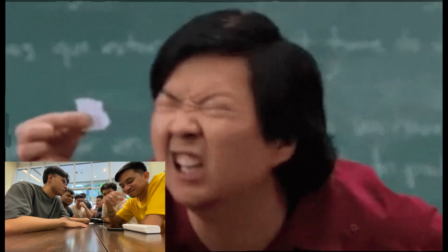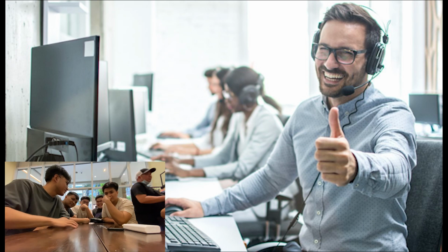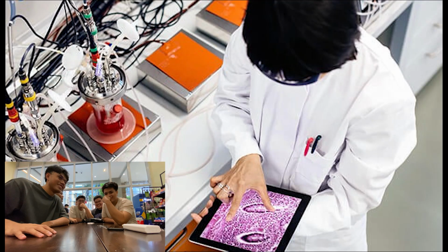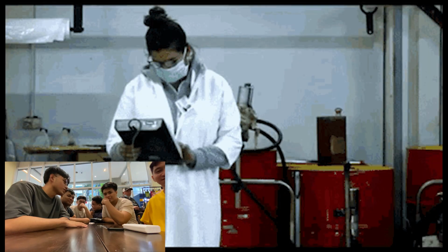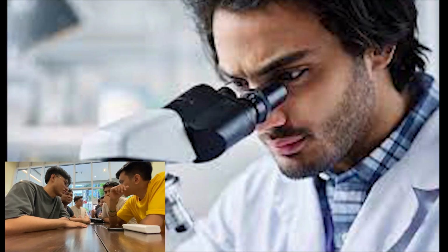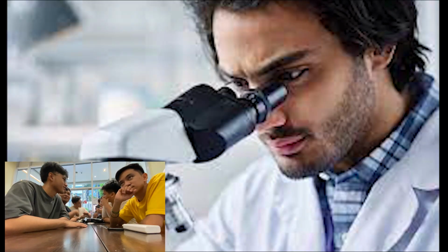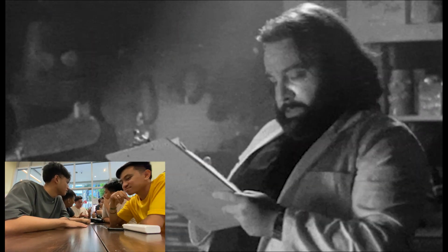Detection: since spotting pitting corrosion with the naked eye is close to impossible, there are reliable ways to test for it. Testing can prevent pitting from wreaking havoc, so we recommend testing susceptible materials often. Common testing methods for pitting corrosion include: the first one is visual inspection. Using a microscope, a professional will count the number of pits in a given area. This helps them determine their size and distribution as well as the intensity.